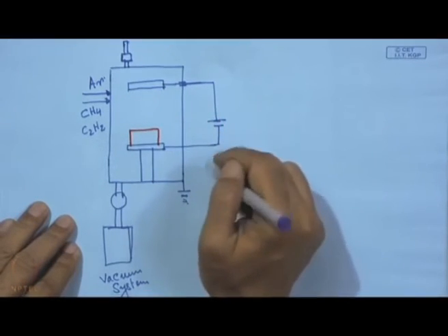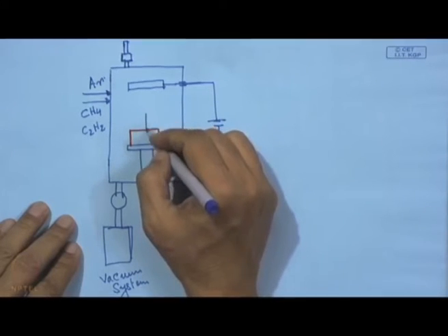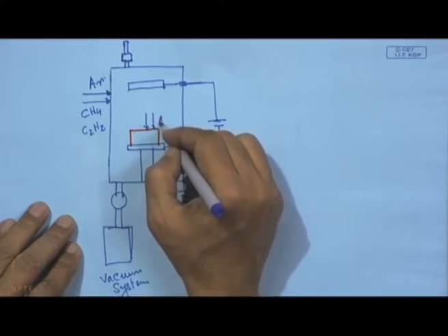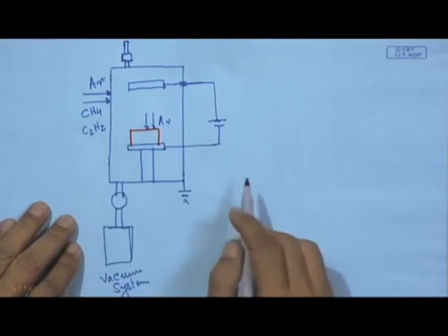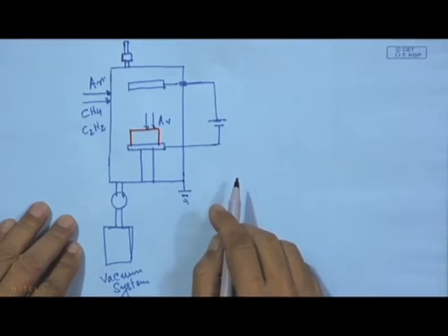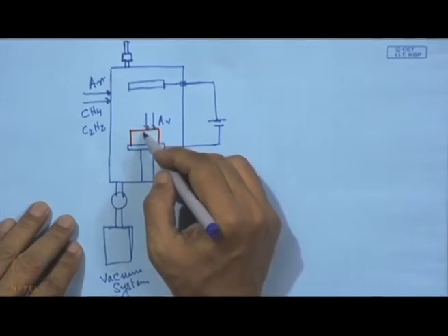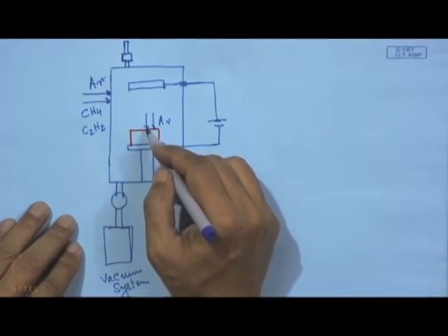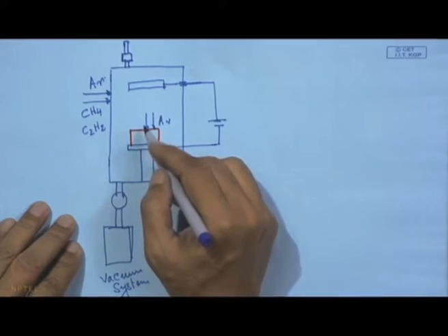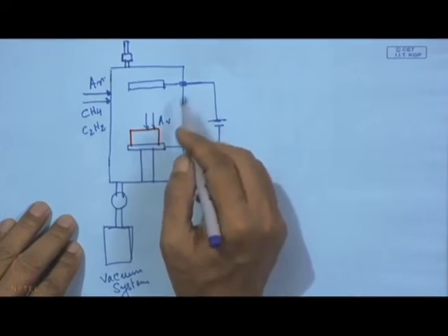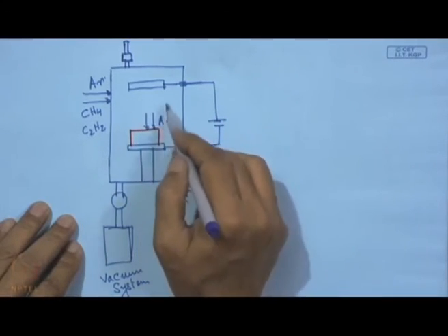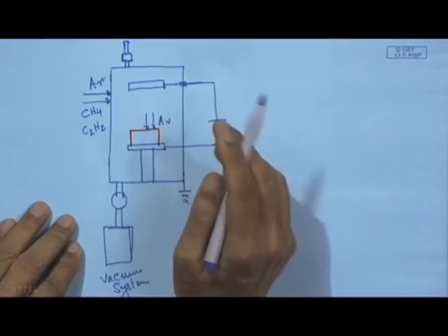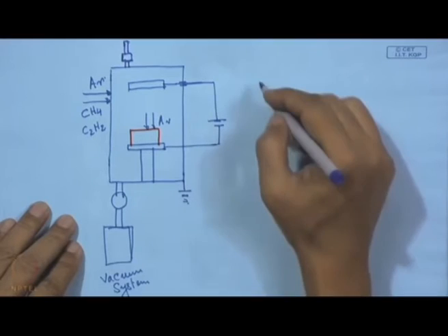With this negative polarity, the incoming argon can clean this substrate, followed by admittance of methane. Then with this discharge of methane, on this surface it will split, carbon will be deposited and hydrogen will be released as neutral. And since this is plasma enhanced or assisted, we can reduce this temperature.